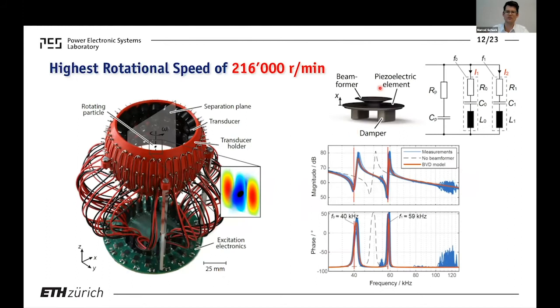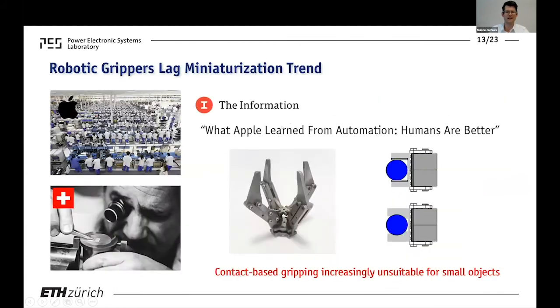If you look at the transducer model, it's a piezoelectric transducer that you can model with an equivalent circuit with multiple serial resonant paths. And you introduce one of these oscillator paths here for every resonant frequency. So quite a high frequency, or quite a high rotational speed already here. We'll see in future experiments if we can still increase this.